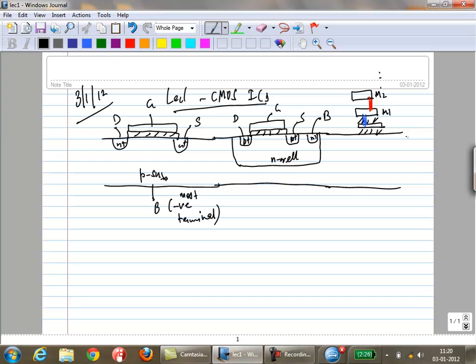However, if you have an NMOS really far away, you may have a central connection to the negative terminal. Obviously the connection for that is going to go through a very resistive path. The actual bulk for that is very resistive. So you probably want to put in local contacts. You might put in P plus contacts and connect it through metal. Let's say this is usually ground.